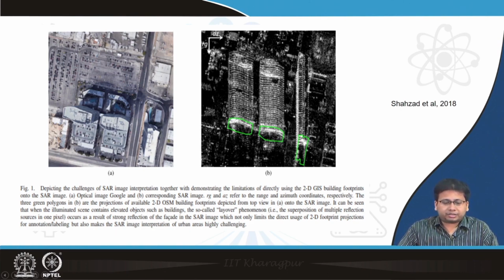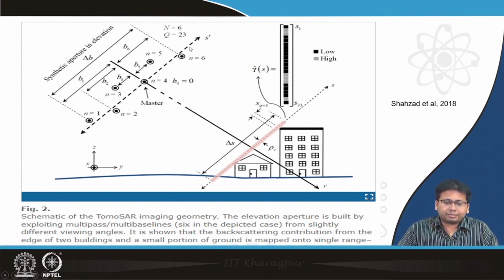Based on these kinds of representations, we have to find the other buildings in similar images. Now when an SAR image is being captured, there are many factors which determine what will be the nature of the response to the building. As SAR is an active sensing technology, it sends out rays, and then the rays are reflected back, and based on the reflection they try to understand, basically they measure the intensities of the reflection and so on.